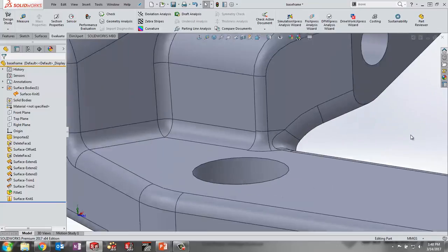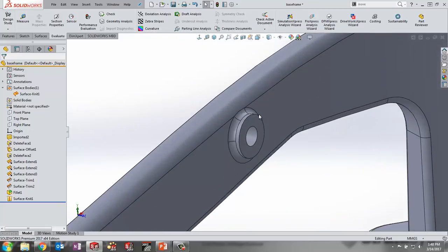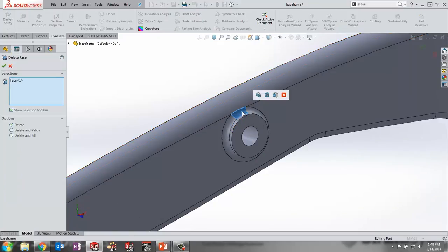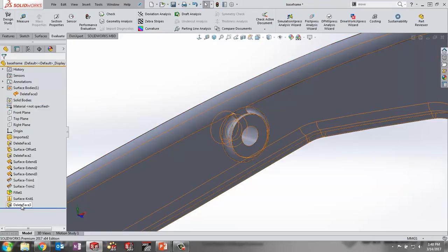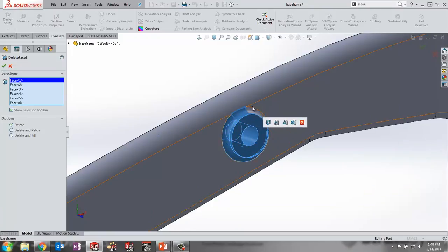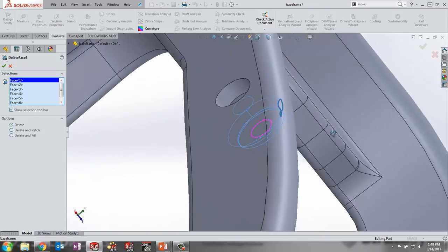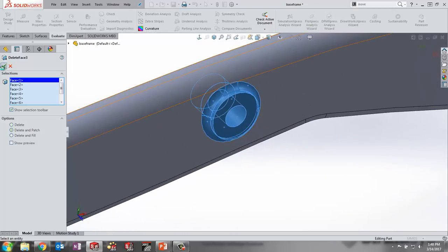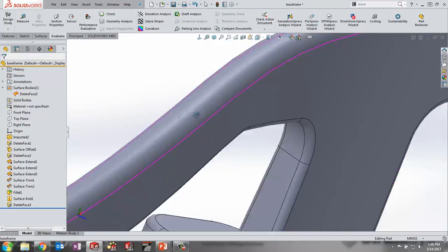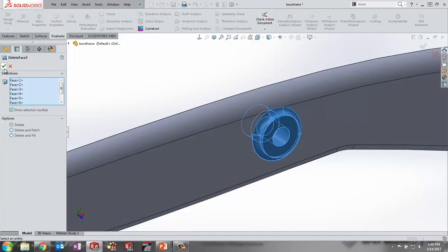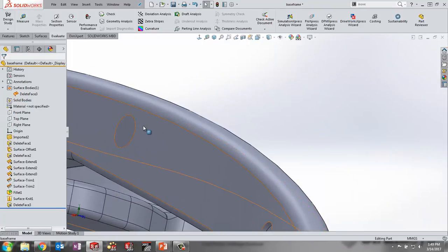Now, also taking a look at some of this other stuff that we've got going on here, we have the ability to remove some more things. So let me go ahead and use my delete here. Whoops, my bad. I'm going to make sure I specify all of these faces in here. This is like what we talked about earlier, using that potential for a delete and patch. If I leave on a delete and patch, you can see that it patches everything together. What if for some reason that delete patch doesn't really work and we want to start with our delete face? You come over here.